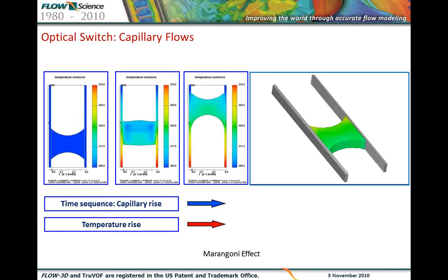This also captures the mass transfer in a liquid layer due to surface tension differences, or the Marangoni effect. Since the liquid with a high surface tension pulls more strongly on the surrounding liquids than the one with low surface tension, the presence of a gradient in surface tension will naturally cause the liquid to flow away from the regions of low surface tension.